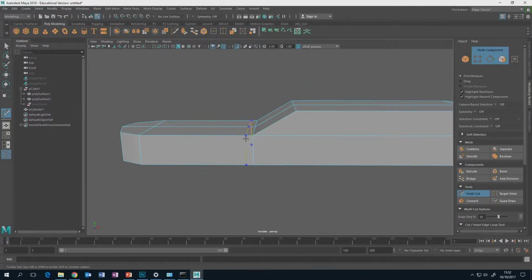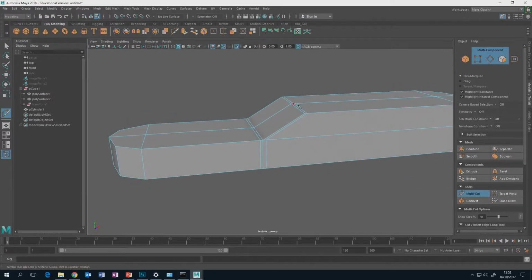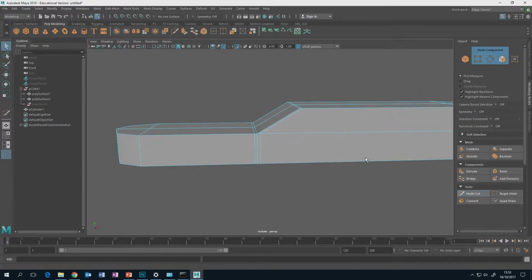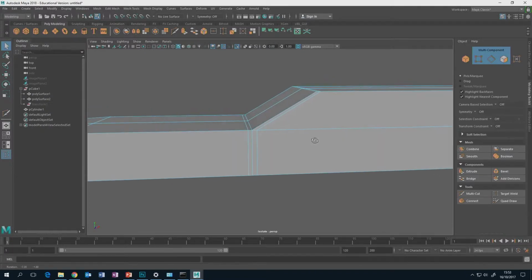So we're just going to put some edge loops where we want it to be a little bit harder. So put one there. And let's put one just here. This will be a good, actually this will show something worth looking at. So put one there. But you notice what that edge loop has done? It's kind of followed the contours around. So we've got the loop here where we want it, but we don't necessarily want this kind of stuff to go on.